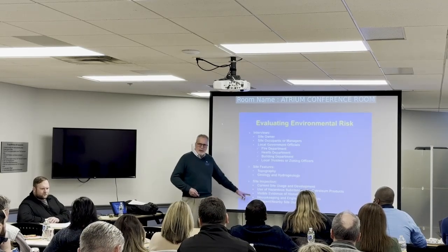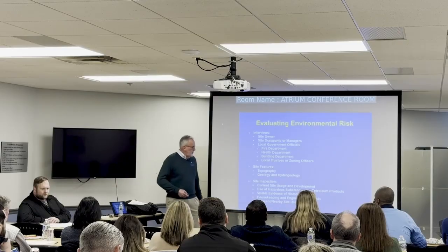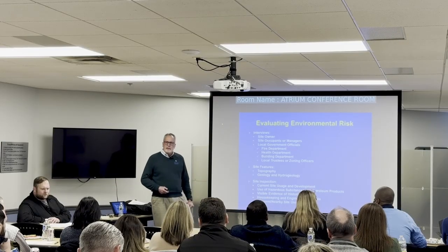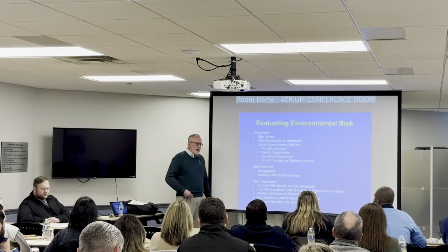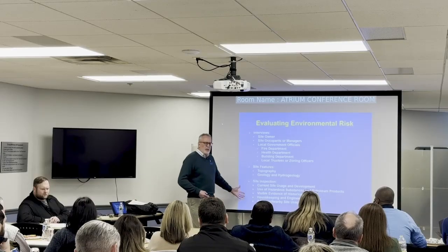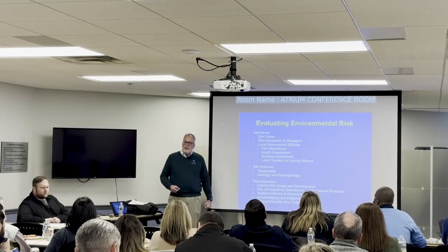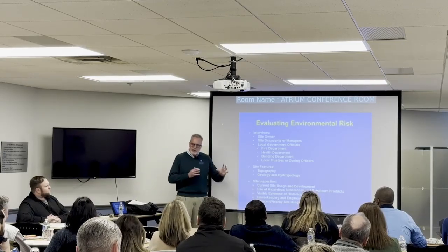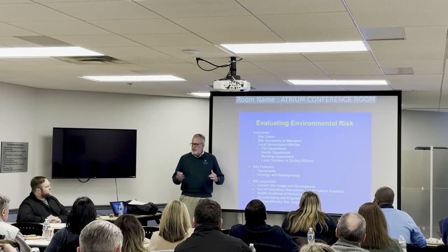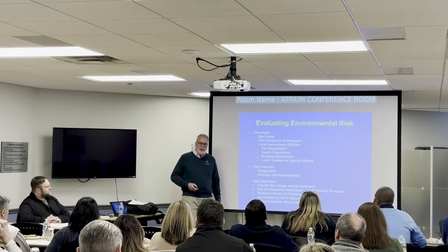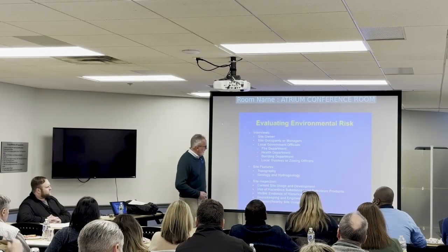And then site inspection. We go out and take a look at the property, take some photographs, and look for things. Look for vent pipes, look for fill pipes, what's going on next door. And we always like to get all the historical stuff first. We get an idea of what the history of the site is, and that gives us some ideas on where these risk items may be.